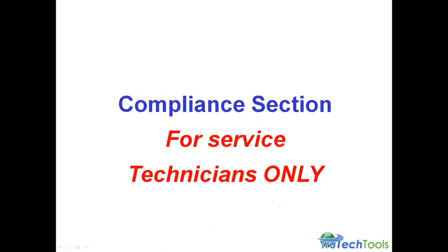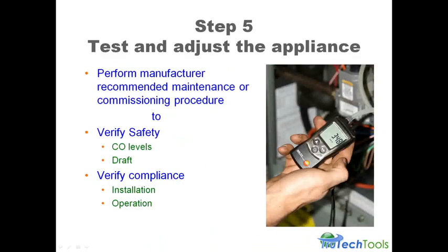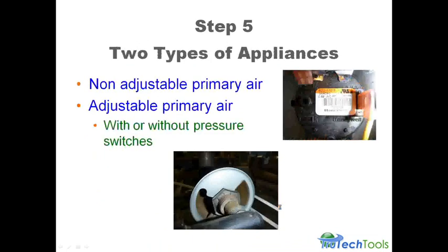This is really for service technicians only. If you're doing BPI testing, you're not going to be doing these adjustments. So now that we've gone through and we've done all our testing, we need to test and adjust the appliance to meet the conformance of the manufacturer's setup, right? We're doing this to verify safety, to check the CO levels of draft, and verify our compliance of our installation or operation.